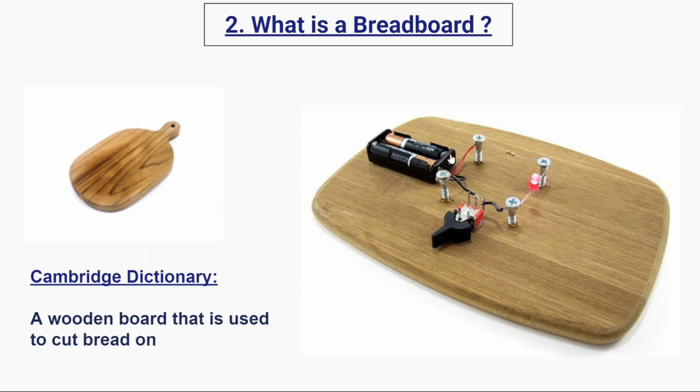It appears to me like maybe an AA or AAA size battery. So it's a 3-volt battery. The positive side is connecting to the resistor, and the resistor is connecting with the LED, and the negative side is coming to the switch. Since the switch is on, you see the LED lighting, because on means this wire is connected from this screw to this screw. So there's conduction happening here. Because of the completeness of the circuit, the current is flowing, and that's why you see the LED glowing.